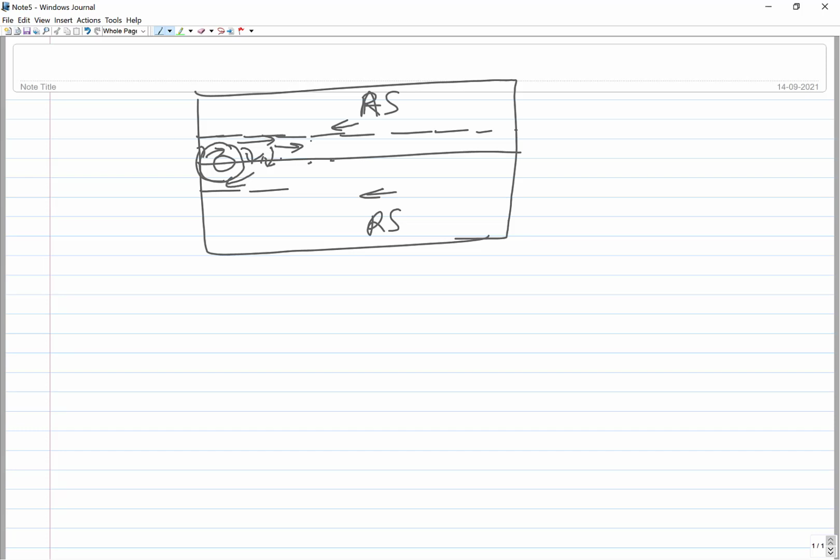Because on the advancing side there will be greater metal softening as compared to the retreating side. So it is not just thermal softening, but the deformation is coupled with the transport or movement of the metal from the advancing side to the retreating side, or from the front side to the back side like this.